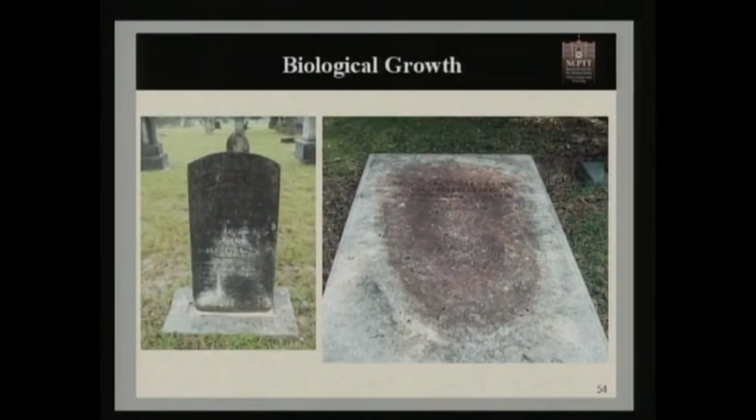Another reason that we do a lot of cleaning, especially in the South where we're working currently and all along the East Coast, is from biodeterioration. A lot of times biological growth, be it lichen or algae or fungi that are attaching themselves to the stone, makes it very unsightly. It makes it hard to read. A lot of these biological growths can actually feed on the stone and help break it down. So this may be a time that we want to talk about biocides, and we'll talk a little bit more about those in a minute. But biocides are a treatment, an additive to a cleaner that actually kills that biological growth and helps it come off.